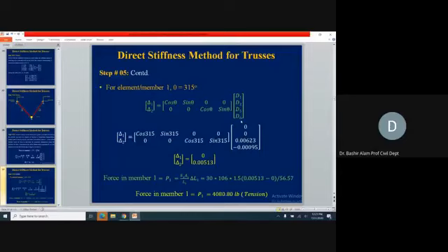And we know these displacements now. So instead of theta, we are putting 315 degrees. For D1 and D2, they were at joint 1 where we had the hinge support, so 0, 0. And D5 and D6 we already found, so I'm putting just those values.